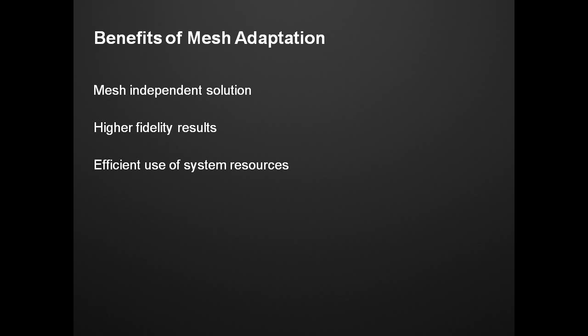One approach to meshing is to over-refine large portions of a model in hopes to capture the final flow and thermal fields. This method will probably provide decent simulation results, but many elements may be wasted where they are not necessary, causing model size and simulation time to increase. Adaptation helps to conserve resources by refining the mesh where needed and coarsening the mesh when possible.